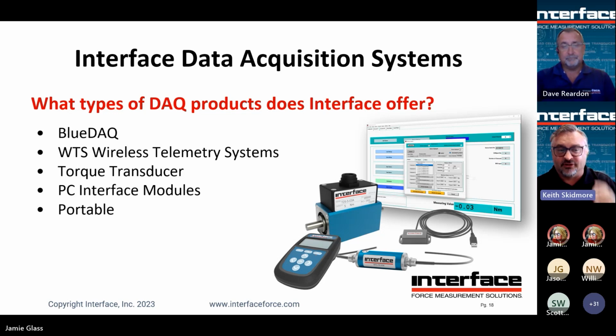Some of the torque transducers have embedded USB amplifiers, so they have a USB connection to the PC. Also, RS-485 is available. That PC connection can be used into somebody else's or their own software, or we do have software that comes with these systems that allows display and logging of data, calculates horsepower, for example, on a torque sensor.